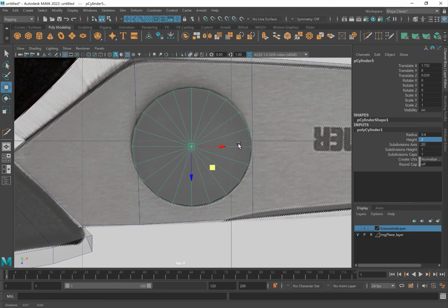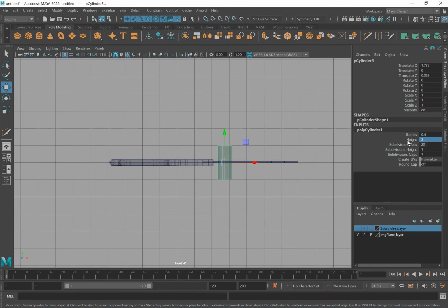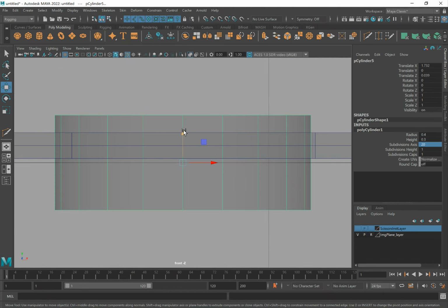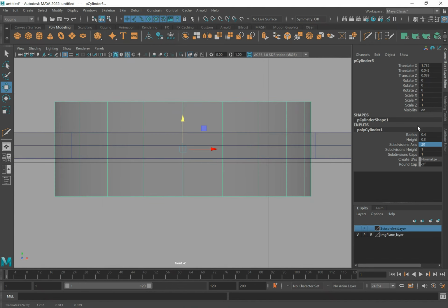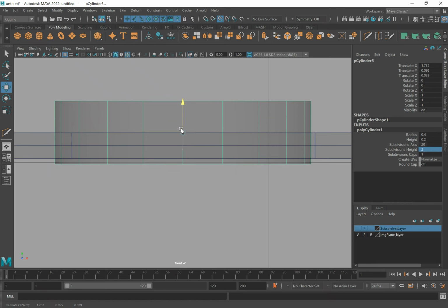And then the next thing is I will need to go to the front view. So the height is a bit too much, so maybe 0.3. Maybe still too high, 0.2. Okay, so 0.2 might be a good height, so I'm just gonna set it to 2 again, so that I'm trying out to do it based on halves, right?